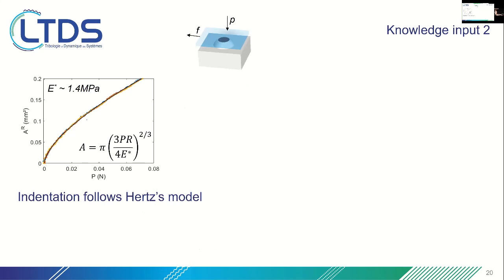Okay, second input is that we want to calibrate the building block of those interfaces, and the building block is the individual microcontact. When you press those microcontacts, then you could find that they follow very well Hertz's model for indentation with an effective Young modulus of 1.4 megapascals.